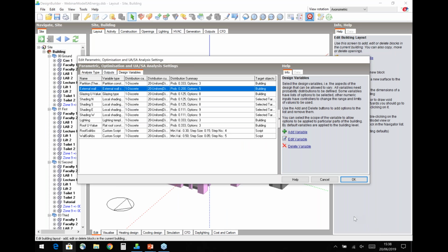The last difference I want to highlight is that we don't have the HVAC system design variable. The HVAC system is a very influential variable for cooling energy, so much so that it dwarfs every other factor. In my initial runs, I found that HVAC system was skewing the sensitivity analysis, and the confidence level values in the results of other variables was not very high.